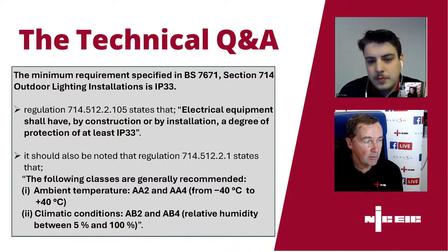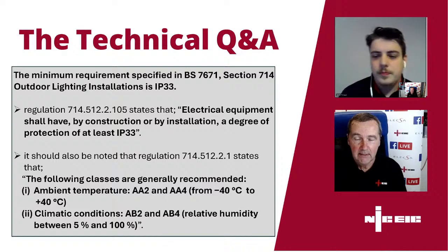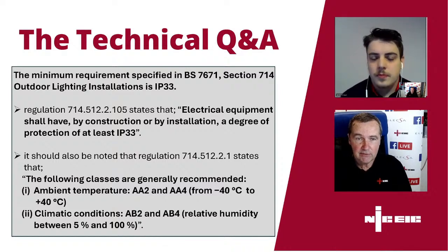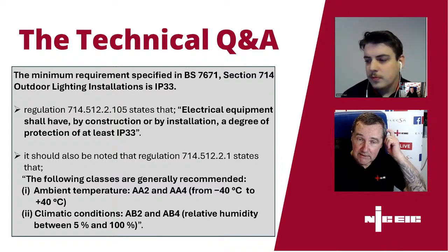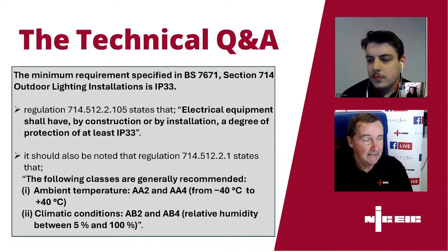It is quite common, especially in large installations where you've got very high currents coming in, but you might be some distance from the supply, which means that even the Ze might be greater than the maximum Zs for your protective device.